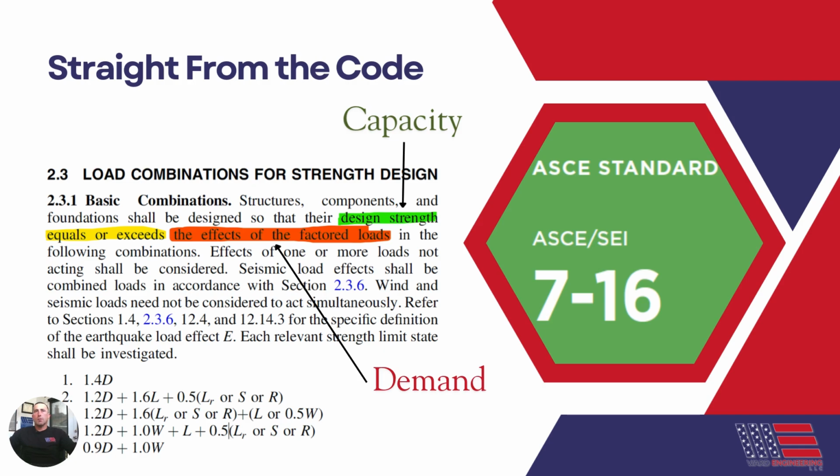And this statement, the effects of the factored loads, is another way of just saying the demand. So if you want to really dial this straight down, it's saying the capacity needs to equal or exceed the demand, which is what I've already said multiple times. So for me, I would argue that this is perhaps the most important statement in all of structural engineering, and certainly the most important statement in this structural document, ASCE 7-16.